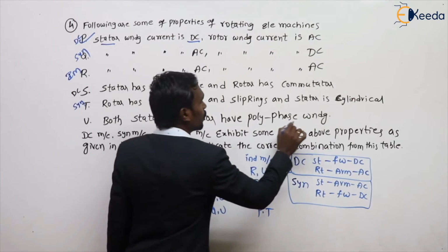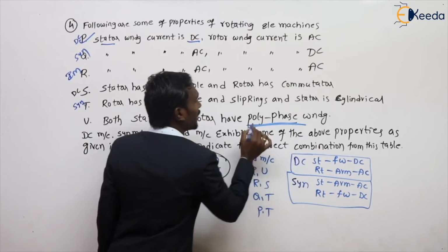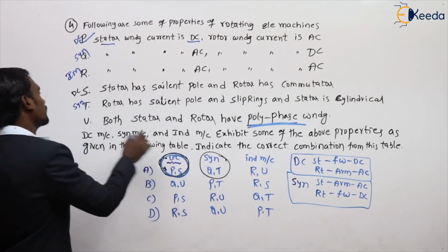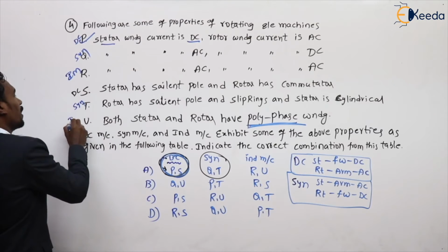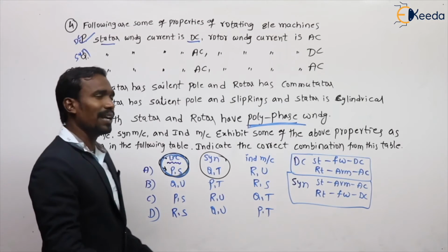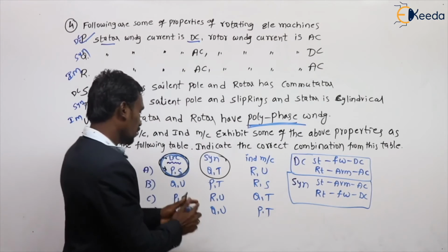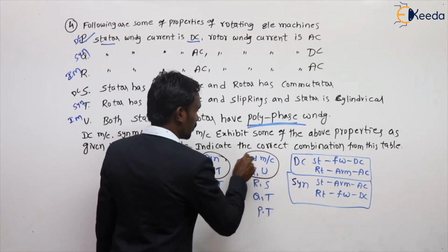Both stator and rotor having polyphase winding. Yeah, 100% correct answer. Both having polyphase. It may be 3 phase, 5 phase, 7 phase, but both having polyphase. So this is also correct answer for induction machine.